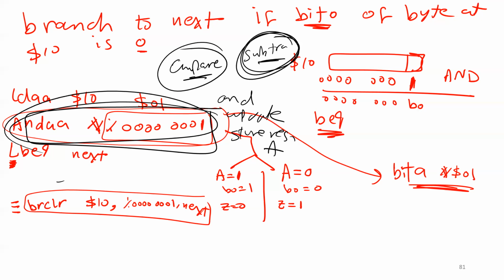Do you want to store the result in A? Do you want to destroy A? No, the answer is no, because I'm not interested in doing AND, getting the result of AND, and using it. The reason I'm doing AND is just to update the flags, similar to compare. You got what I'm saying?